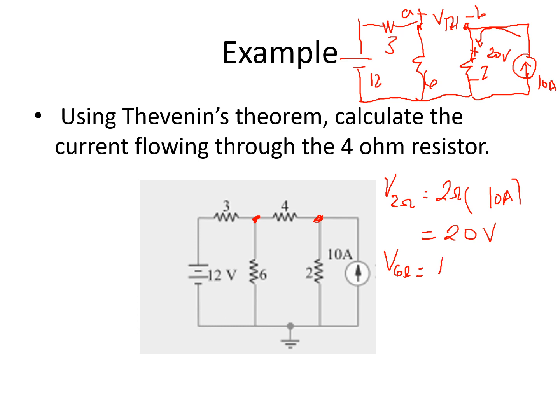So that is your total voltage, 12, multiplied by the value of your 6 ohms, because we wanted to know the voltage drop across your 6 ohms, divided by the total resistance, which is 6 plus 3. So the voltage across 6 ohms is equivalent to 12 times 6 divided by 9. So the voltage is equivalent to 8 volts.